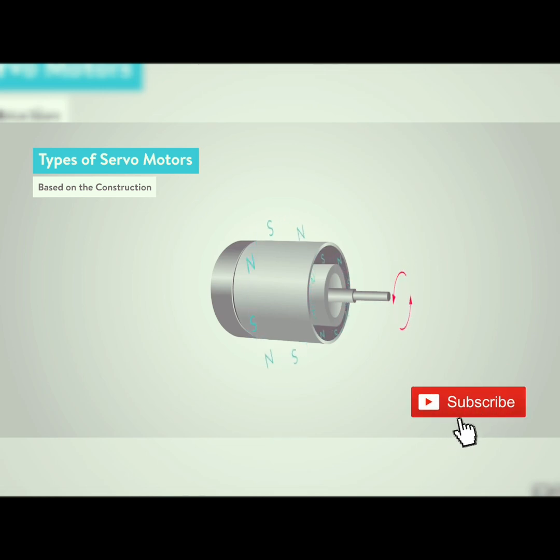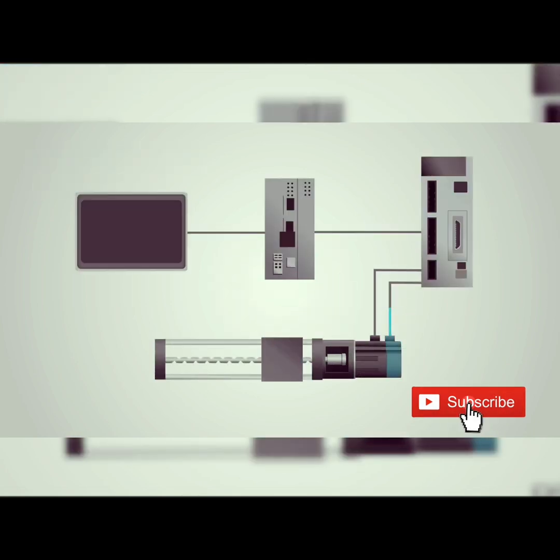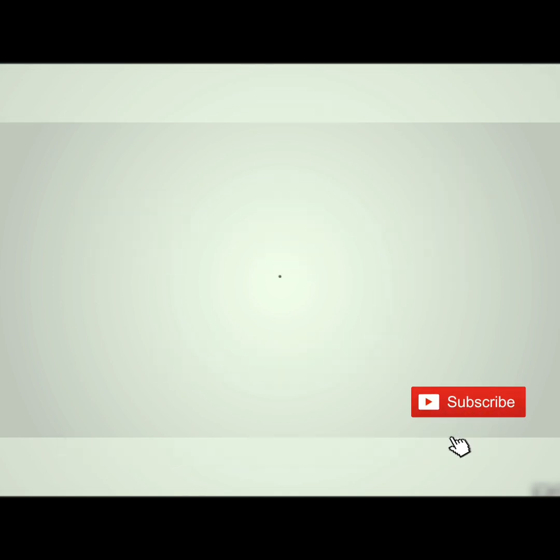With this permanent magnet rotor, no rotor current is required. So when the stator field de-energizes and stops, the rotor also stops. These motors have higher efficiency due to the absence of rotor current. When the position of the rotor with respect to the stator is required, an encoder is placed on the rotor and provides feedback to the servo motor controller.